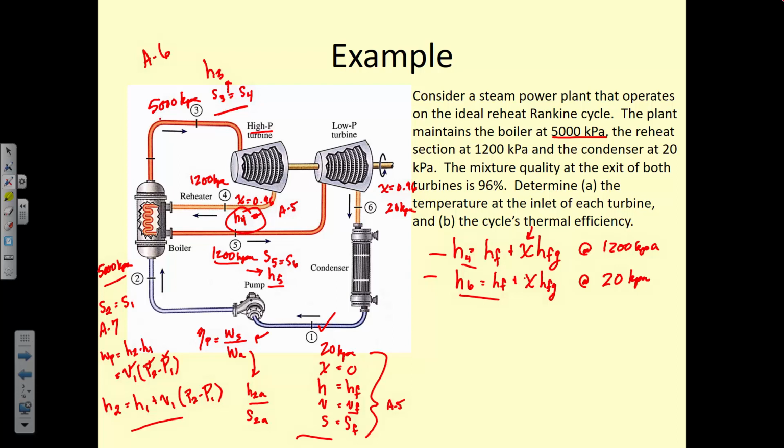So you find, at this pressure, where S3 is equal to S4, and that will give you your H3 in the tables. And if you have an interpolation function on your calculator and you haven't figured out how to use it yet, I would recommend that you figure it out, because there's some interpolation on this exam. If you do it by hand every time and you're quick, that's fine. But make sure you know how to use it and you can tell when the answers are garbage because you plugged things in wrong. So don't always rely on it and just take whatever it gives you. Make sure you have a good sense of a ballpark of what the answer should be. So do a reality check.